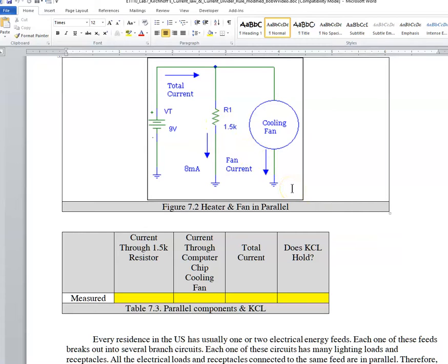In the case of the fan, if we did use that, you would see an increase in the current of the fan as you slow down the fan blades by pressing against the blades with your finger. In other words, an electric motor could vary the amount of current that it draws by the speed at which it's running. When you first start the fan, the current would be higher.